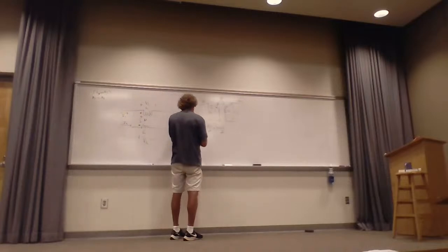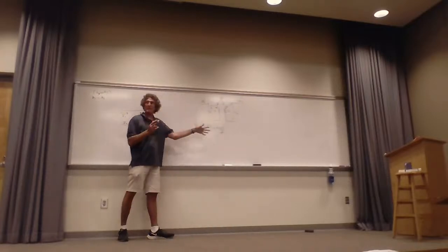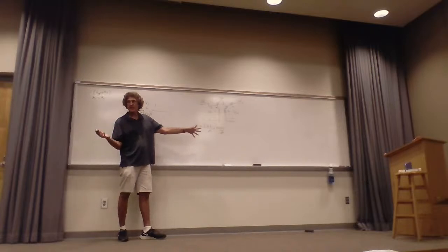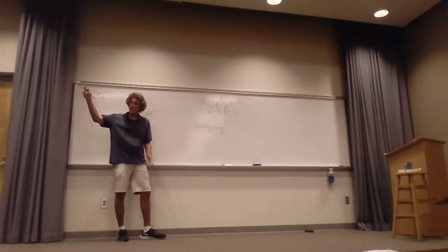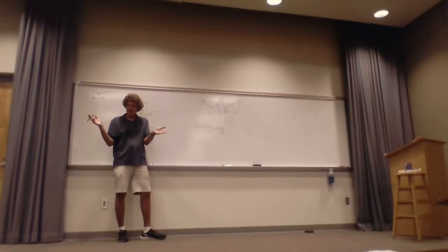If I look at V2, better yet, y'all give me this. If we're at steady state at a constant frequency, what I can do is pull out a j omega, right? If you have d/dt and you're in the frequency domain, it just pulls out a j omega, doesn't it, class?